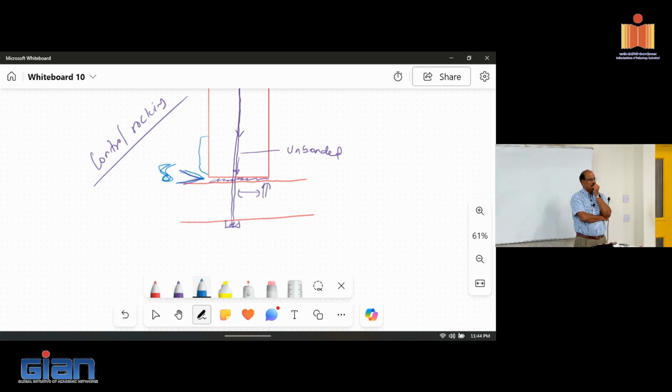So, I'm just going to raise an interesting question over here. Because the movement can happen both ways in a seismic or wind condition, let's say a seismic condition that we are speaking about. You have symmetrically placed unbonded strands on both sides, closer to the ends of the wall. But the question was, in this case, when major cracks open at the bottom, then there is no real plastic hinge developing, correct, in the wall itself. And so can ductile detailing then be eliminated in the wall? Correct, yeah. Basically, yes. The answer is yes.